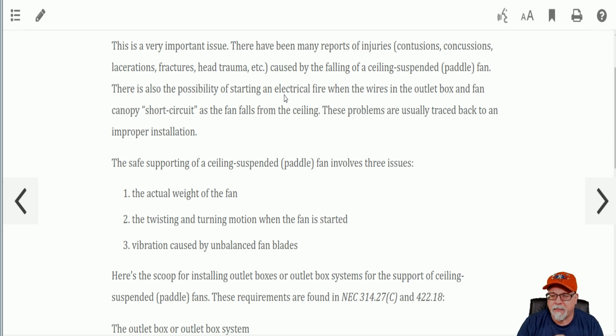Not every fan is balanced. It might look like you have a fan that makes a warble sound or whatever, and we do our best to balance it out. But if a fan is not perfectly balanced, it creates this vibration. And again, 632s, or 832s if you will, that are only held in place by the 832 thread count could wear loose. And that's a big problem with plastic boxes.